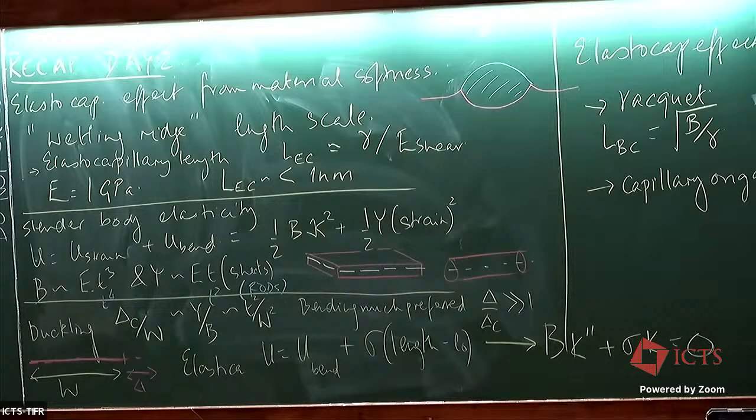The question is, when do you start seeing effects of the speed of deformation of objects? Everything we've talked about is quasi-static, and will be till the end of this hour. The thing you have to work slower than is the speed of sound. Typically things here move very quickly, and it is not difficult in the normal things we do to be in this quasi-static regime.